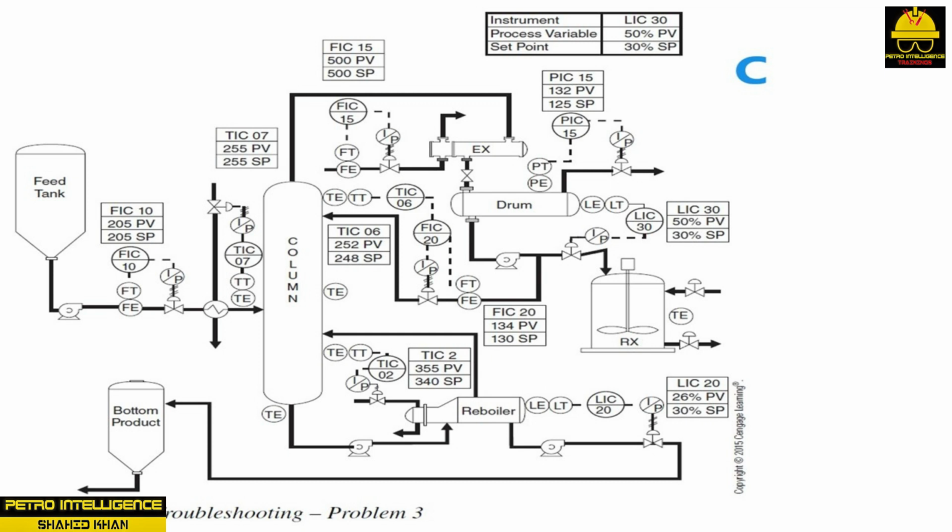Local flooding is when excessive liquid flowing down a column blocks vapor flow up the column in one section. Technicians will typically break a flood by decreasing the feed rate, the reflux rate, or the bottom temperature. Overloading is best described as operating a column at maximum conditions. Weeping is a phenomenon that occurs when the vapor velocity is too low to prevent liquid from flowing through the holes in the tray instead of across the tray. Differential pressure is reduced, and product separation is reduced.